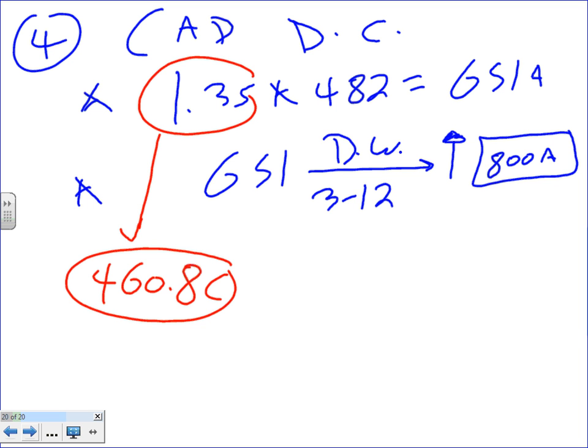For the test, when I give you guys a test, if the sizes are within these ranges, please feel free to use the table. If the sizes of the kVARs are within these ranges, use this table, no problem. But you're going to see when I give you a size of 400, how would you do it for 400? It's not there, so you have to do the calculation that we did. For 400 kVAR, it's not there. It doesn't go that high. Manufacturers of capacitors, guys, have tables like these that give you the size and all this good stuff. If you find one of these from them, feel free to use it. Otherwise, the calculation that I gave you is very close.